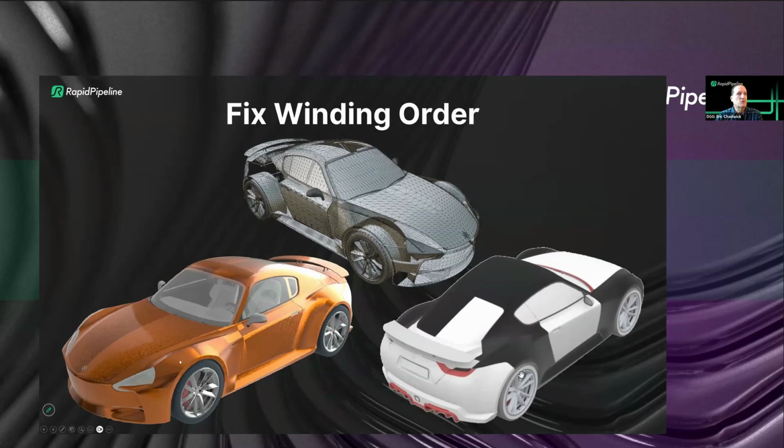And then it's going to have trouble trying to figure out how do I use a normal map on this, or how do I use anisotropy, or anything that is view dependent or angle dependent in the shader. It's going to have problems processing that. And additionally, when you go out to real time, typically those are single-sided and things are going to look inside out in a real-time viewer.